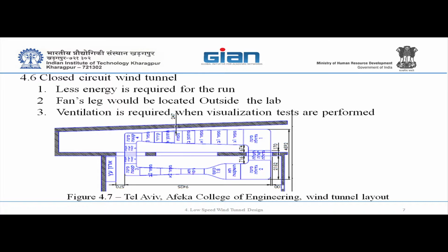So from there we go to another section, transposing from round cross section to square or rectangular, and then you have the third corner, and again the fourth corner prior to the test section, the settling chamber. Again, you prefer them to be identical if possible, not to take care too much of diffusing the size there, so you save again the double design cost and manufacturing efforts.